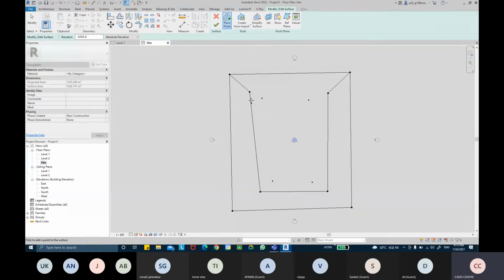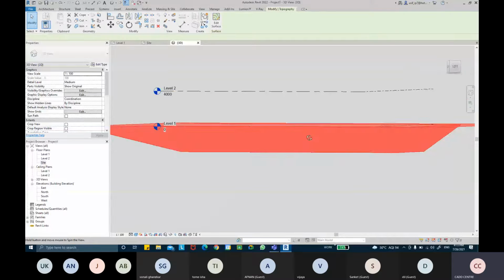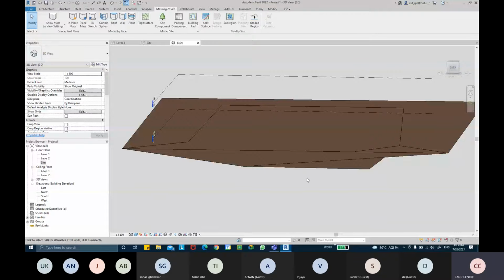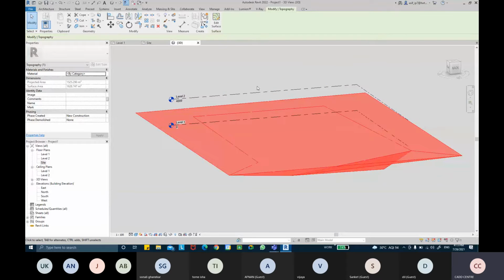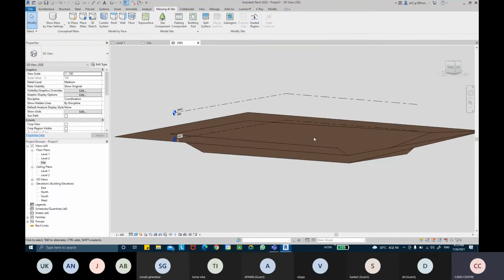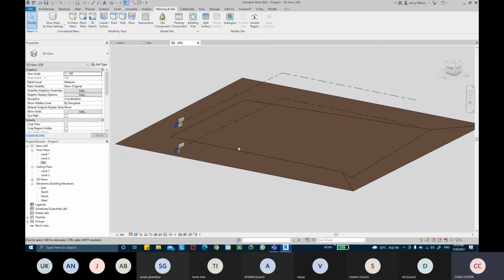It's not smooth, but a little excavated, basically. When I select this topo surface, you can see the projected area and the surface area of it. Okay, and I want to fill that topo surface and make it level, meaning I want to level the ground completely. The surface is that deep, so I need to level it. To level the topo surface, I will have to fill it, I will have to fill the topo surface. Okay, it's 3 meters deep, so I have to fill the surface up to 3 meters. So by making an additional graded region we can fill the surface.